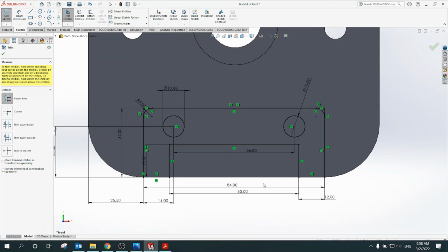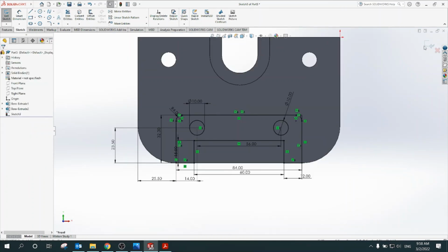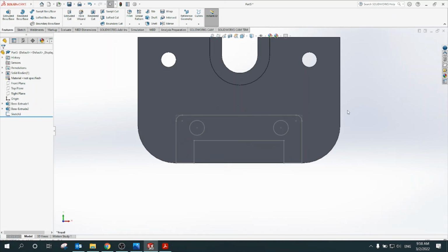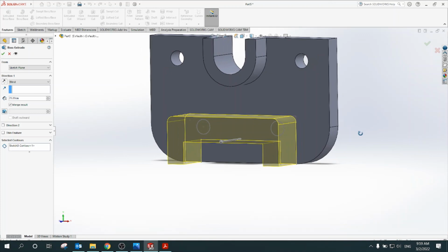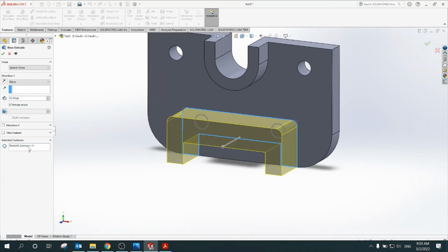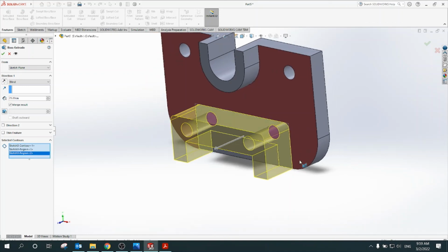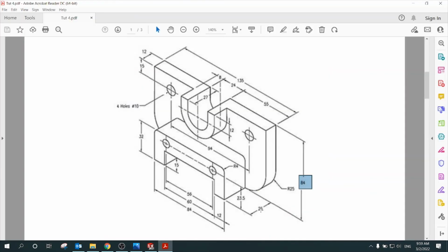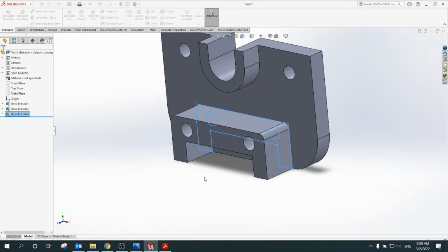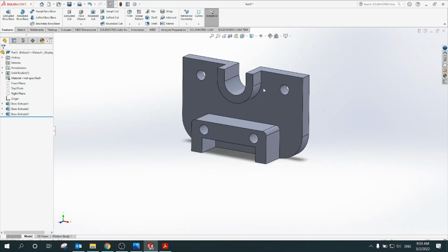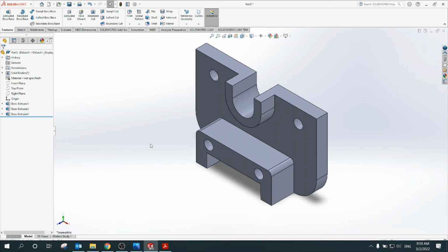So I don't have any line in here, so that when I extrude I will get only this shape. So when I confirm the sketch and extrude, click any point, I'll get this N shape, but I have to move out the small circles, and the thickness of this shape is given to be 25. It is 25 and confirm. So this is the final view of the shape, and that's it.